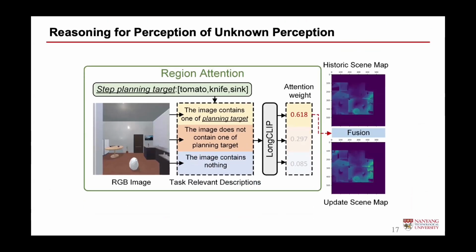So in the above pipeline, the most important thing is that we need to build a good online scene map. This is a little bit different from low-level tasks like 3D segmentation or object detection. We need to figure out the spatial correlation and the semantic correlation among different objects in the indoor scene environment. So actually, we need richer semantic information of this scene. We will update the scene map like this. We extract the visual features for each pixel in the RGBD images by a pre-trained model, like ConceptFusion or something like that, and project the features in the top-down view to build the scene map.